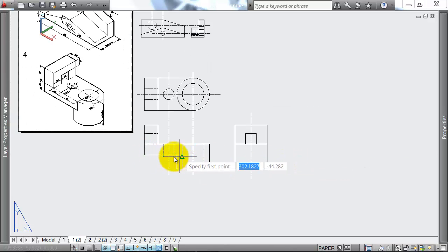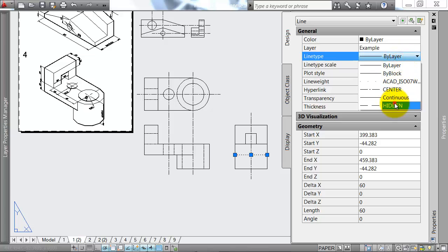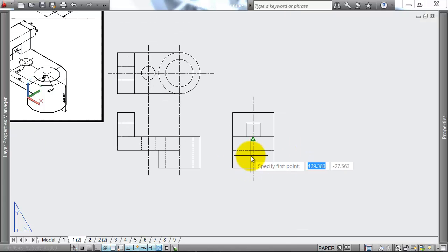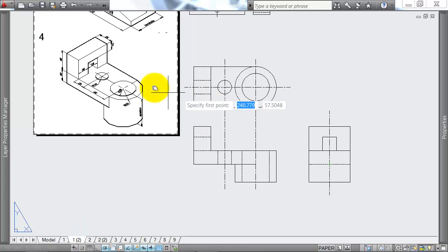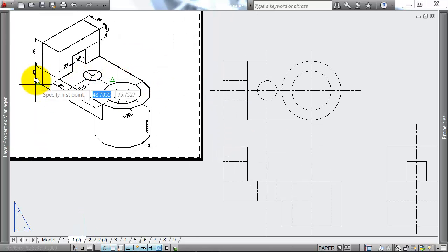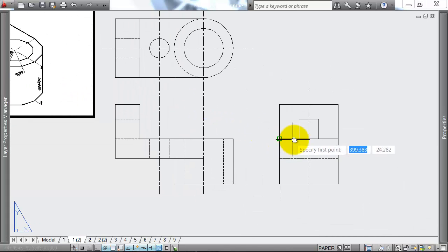This edge down the bottom here, we wouldn't see it as a hard line from the front, but it would show up as a hidden line underneath, going in like so. And we'd also have hidden lines, one for this hole, which is going to be 20 units long, because the hole is only going through a 20 unit piece of material.